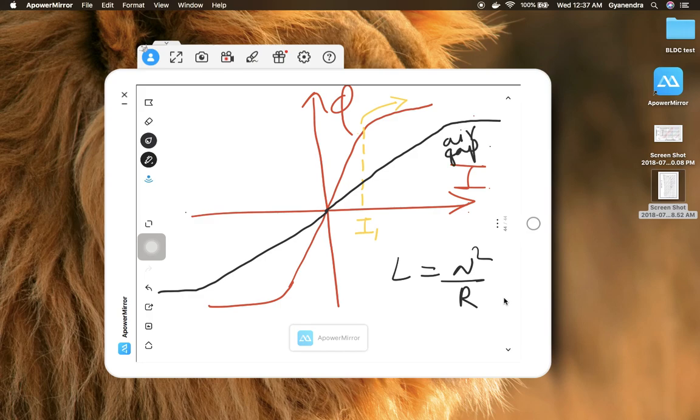The black one is representing what it will be with air gap. But if you see the advantage here, the current which was saturating the core without an air gap will not saturate the core if there is an air gap. So basically the current required to saturate the air gap inductor will be higher than without the air gap.